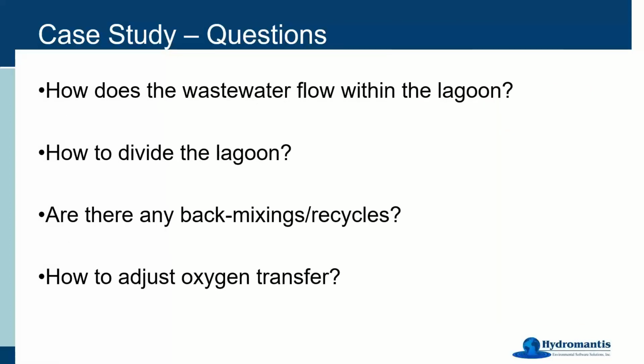So before modeling the lagoon system, there are a few questions that need to be addressed. The first and foremost is, how does the wastewater flow within the lagoon? As Spencer mentioned before, lagoons may have quite complex and dynamic flow paths, but more often than not, they don't have sufficient data collected on the flow within the system. And this is especially true in this case study, since we don't have the resources and time to do experiments such as tracer testing or computational fluid dynamics, we have to rely on the operator's experience in determining the flow pattern.